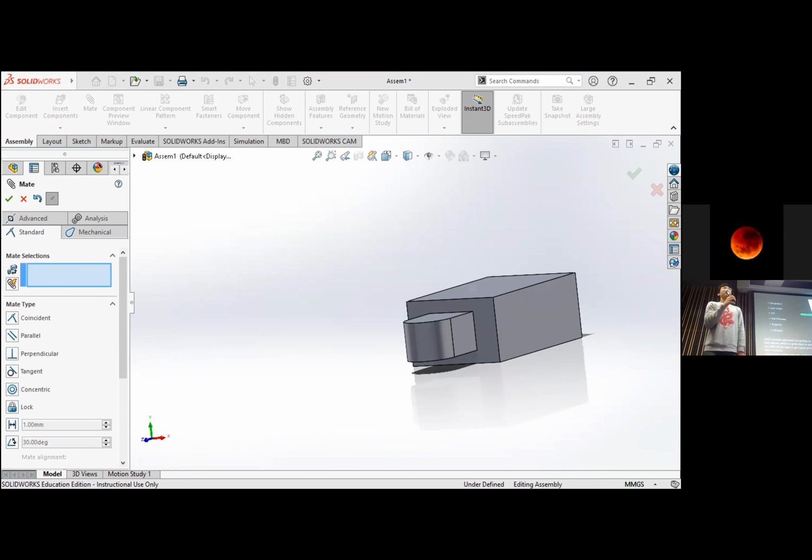One of the most important is temperature. We should set that to each filament type, and each filament brand will have its own temperature, so you kind of have to experiment with it. But usually 200 degrees for the filament and 60 degrees for the bed when you're printing PLA is good, because we usually print in PLA nowadays because it's easy to use and it's pretty cheap. And it's also quite strong, actually.